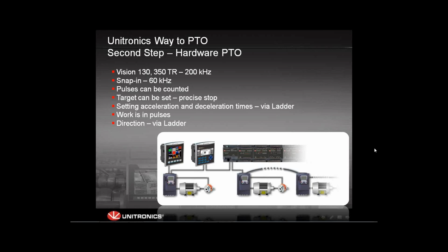Setting the acceleration and the deceleration times was conducted via the ladder. You had to program the ladder so that on a certain pulse the PTO will stop the pulses.